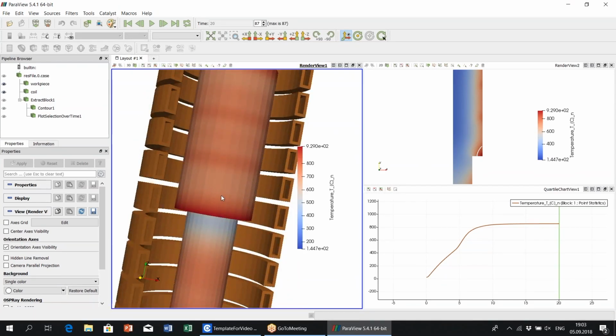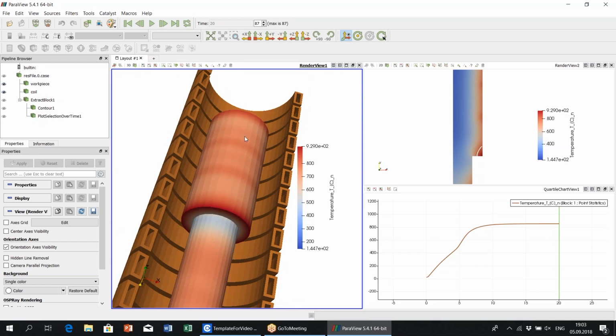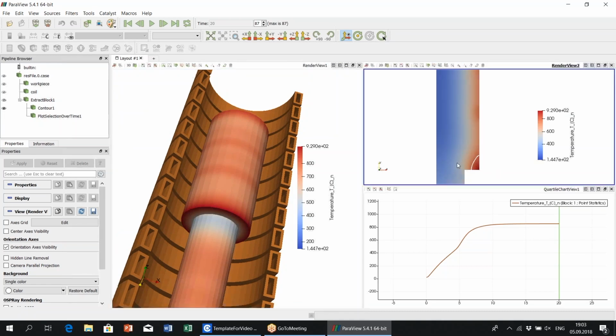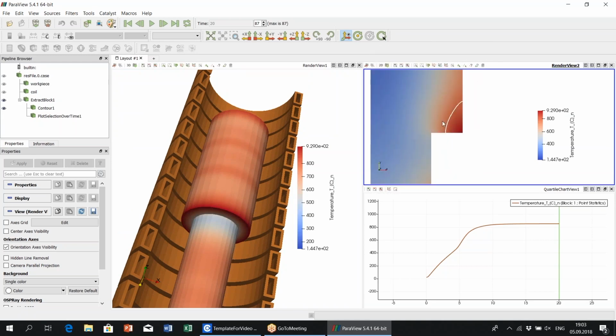In this particular case, you'll note in the cross-section view the blue area on the edge below the step. This may be a potential failure point, as you can see the area clearly did not get heated sufficiently to cure the metal. So you may want to run another simulation with, for example, a lower power frequency to more deeply penetrate the metal in the simulation.